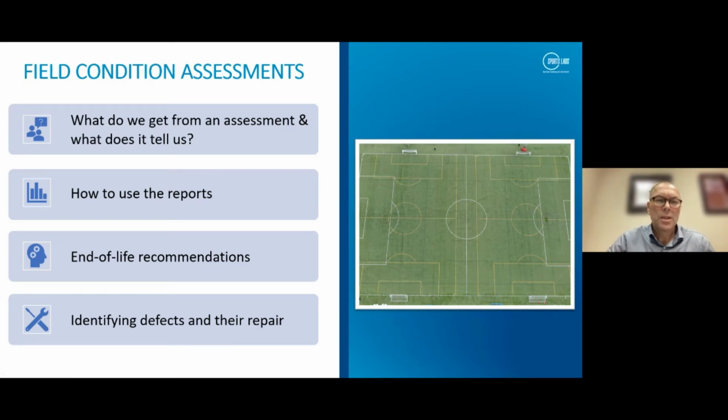It depends on the type of client that really is looking for condition assessments. Mark didn't cover that we are even asked to go in and assess a new field because there may be an issue with it. It could be that the install's not been up to the required standard, or there may be latent defects in the materials that have been supplied, stripy turf, loose fibre, or loops in the fibre which are causing a hazard.